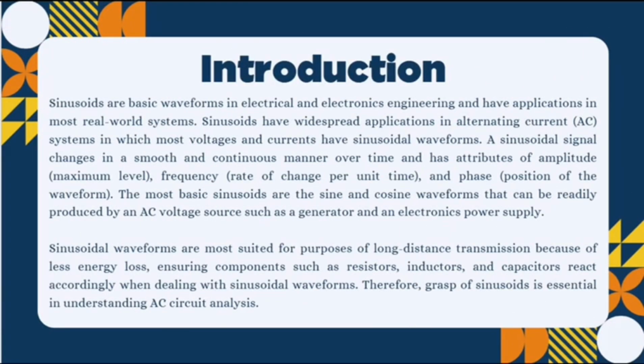For the introduction of sinusoid, sinusoids are basic waveforms in electrical and electronic engineering and have application in most real-world systems. Sinusoids have widespread application in alternating current, which is the AC system, in which most voltage and current have sinusoidal waveform. A sinusoidal signal changes in a smooth and continuous manner over time and has the attributes of amplitude, which is the maximum level, frequency, which is the rate of change per unit time, and phase, which is the position of the waveform.